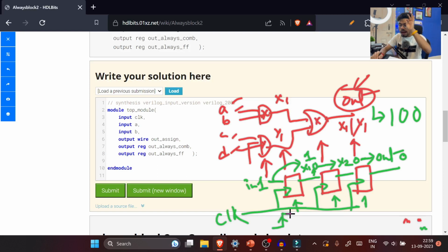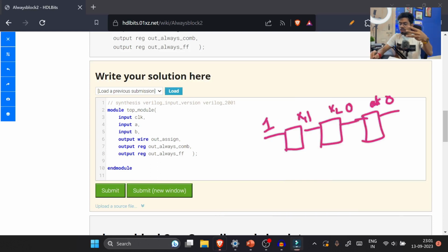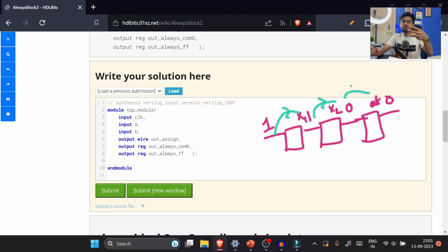So now I need to hold this value, this 1, this 0, this 0, till the time I get the next clock. Anytime I get the next clock edge, I will again give something here. For example, I have given 1 again, and things will follow. One thing you need to observe here, how many things are happening in one clock or in one instance of time. Your circuit is doing three parallel jobs here. 1 transfer, 2 transfer, 3 transfer.